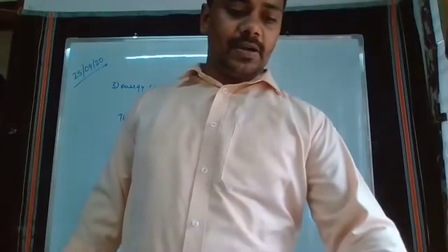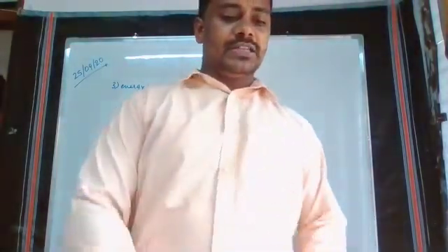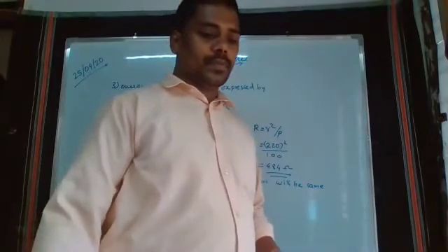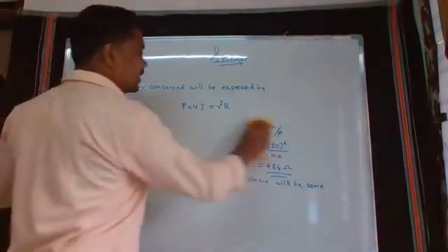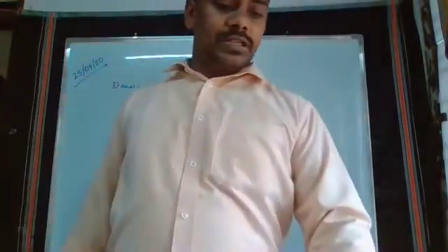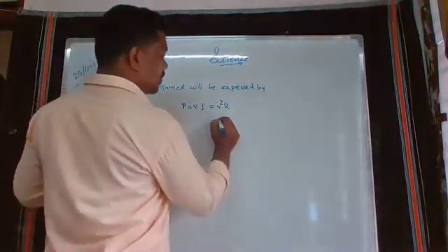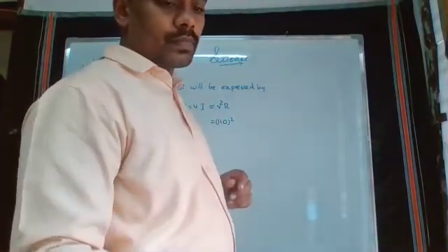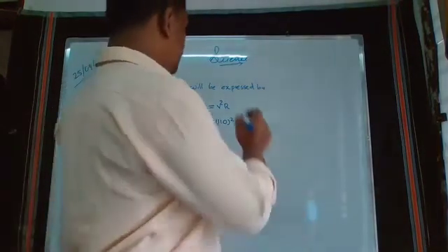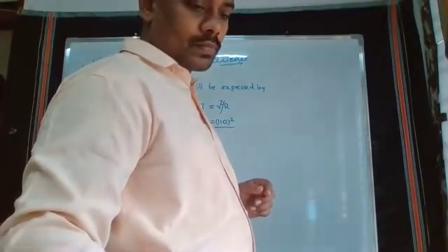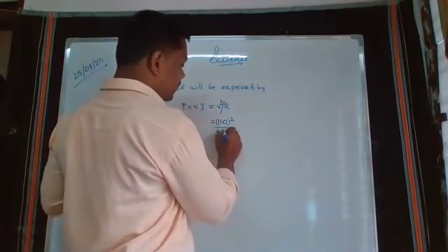Okay, if the supply voltage reduces, the resistance remains same, then power consumed can be calculated as the same V square by R. Substituting the value, we will get 110 all square by R, for 484 ohm.